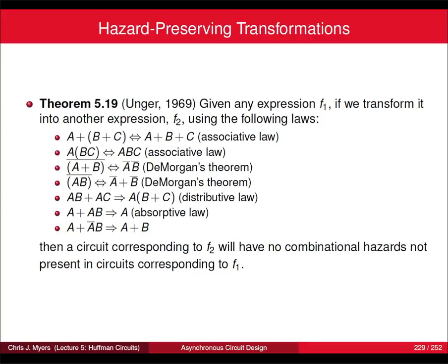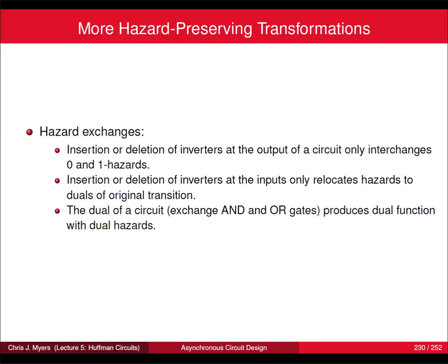So these supposedly redundant products that we've added to cover hazards are going to get eliminated by a simplifier. Because the simplifier is going to go, oh, I've got some other product that covers it, not realizing that product is in there to cover a static hazard. Does that make sense? So we have to put some shackles on a multi-level synthesis engine and tell it, I've put that logic in there for a reason. Don't simplify it out. Basically, you can't let it do the simplification.